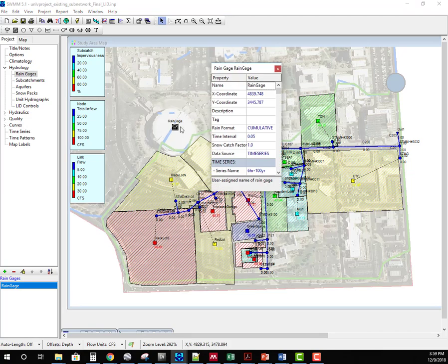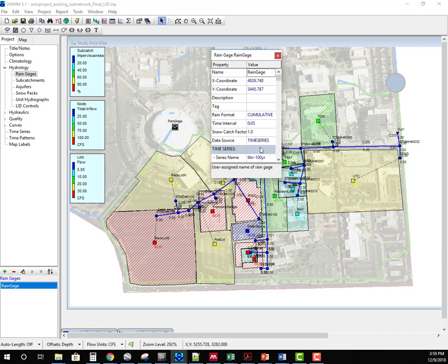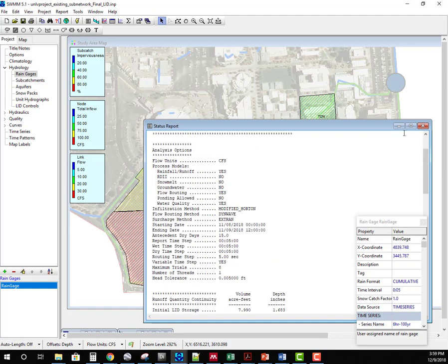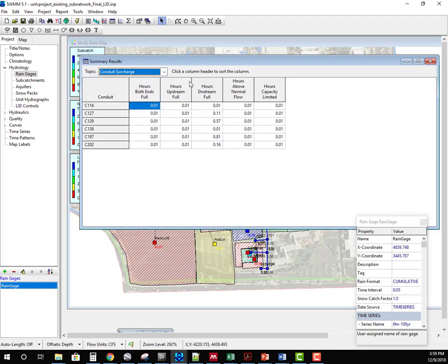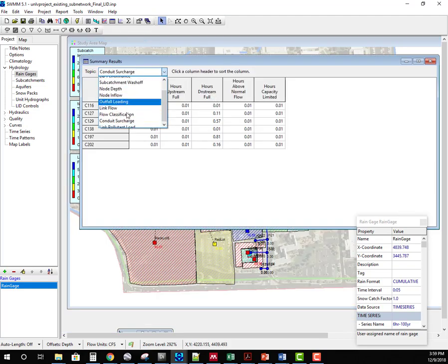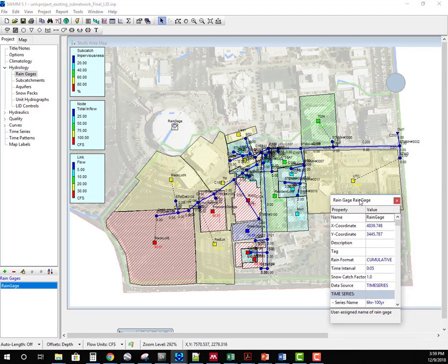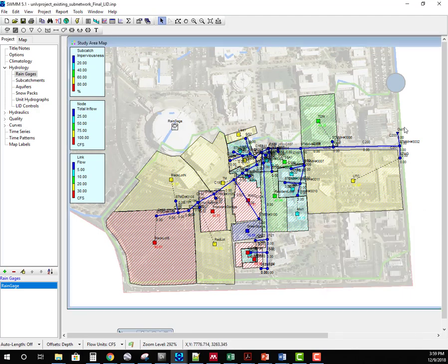and we can see the continuity error is very small, and we are just making sure we are using the correct rainfall. And let's see if we got any flooding by seeing the status report as well as, more efficiently, the node flooding. So we can't see any node flooding, but we do have some secondary surcharge, which means we are getting some pressure flow, but we don't have any flooding. So we successfully removed the flooding from the already existing pipe system using the LID controls.